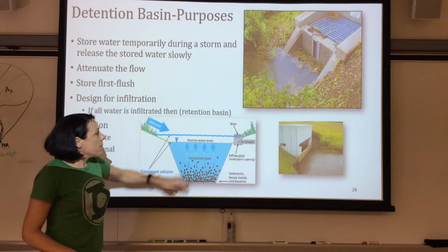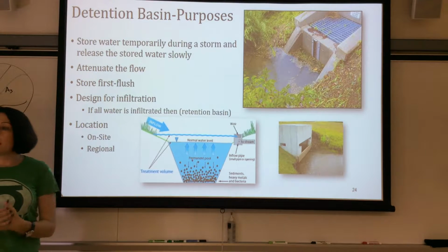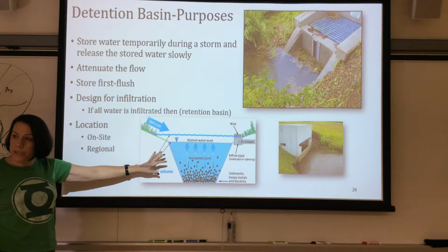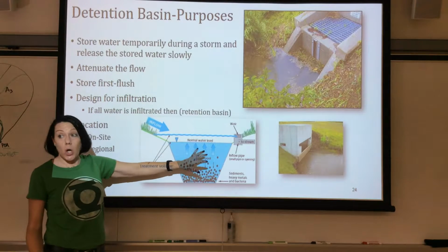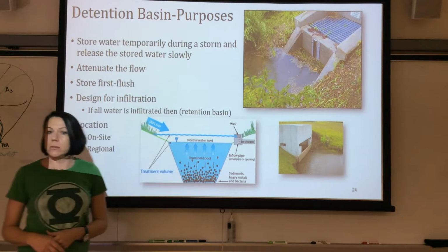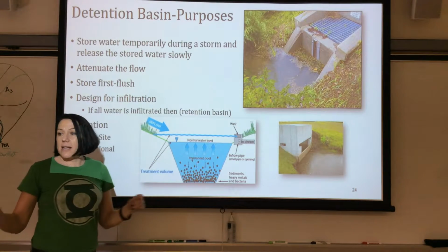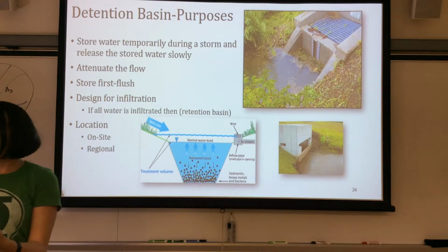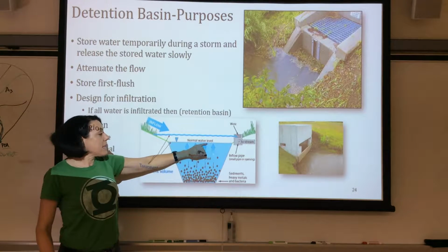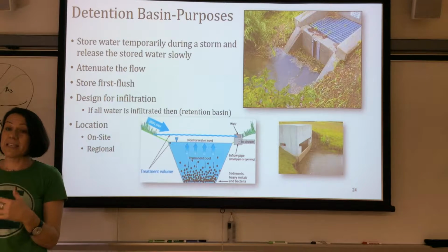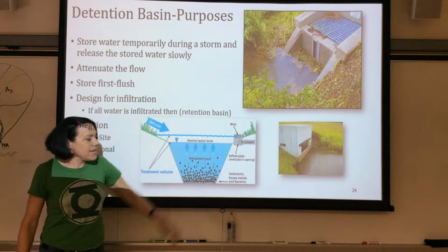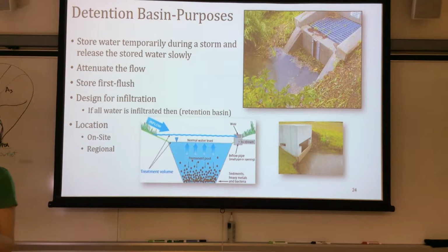Now, here is our pond. It is a retention or detention basin. We detain just by holding the water and releasing it. We retain if we hold all the water and let it infiltrate into the ground. There's a thing called permanent pool. Remember how I said last time we can use control water elevation, surface water elevation, normal water elevation is another one, and anything below that water elevation that is continually held in the pond is called the permanent pool. And all these little dots are sediment and heavy metals or anything settling down to the bottom.